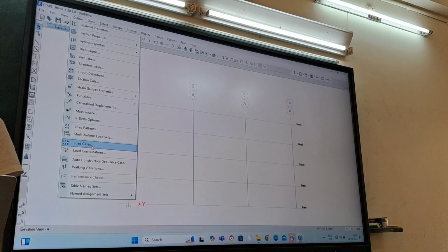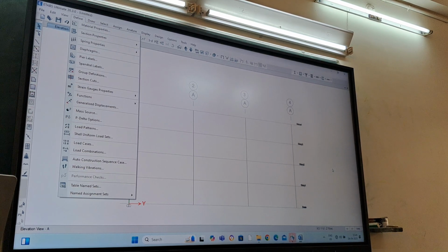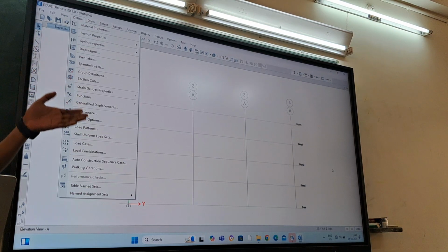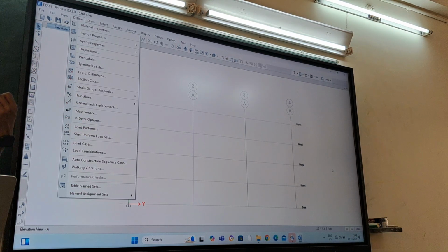Next we need one load pattern also. In this case, it means load time history. For example, you know an earthquake time history. You have a predefined time history. When you apply this, the structure follows this time history, and for each of these points, it calculates how much force and deformation occurred in the structure. The same approach we are going to apply here.